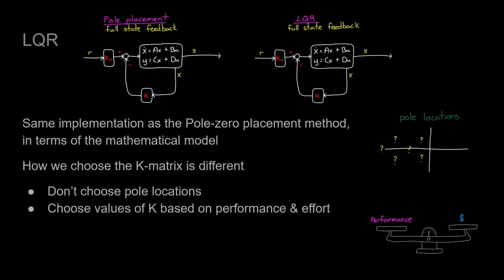So it was quite just trial and error to use a PID system. The tuning that I did there, changing the values, is quite unintuitive. It could work, just a lot of trial and error. But I went back to the previous system with the pole placement system, the full state feedback, as they call it, because it's a closed loop.